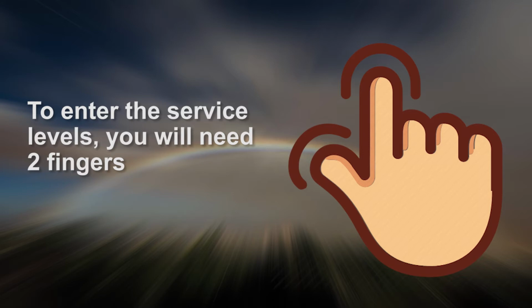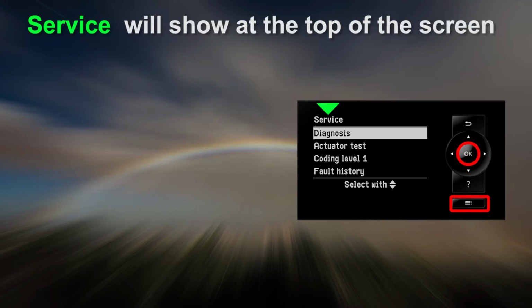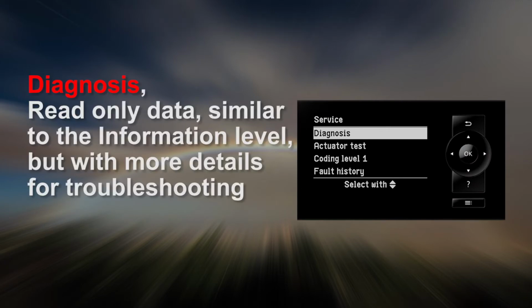To enter the service level, you'll need 2 fingers. From any screen, using 2 fingers, press and hold the OK and extended menu keys for about 3 seconds. Service will show at the top of the screen. The diagnosis level is read-only data, similar to the information level, but with more details for troubleshooting.